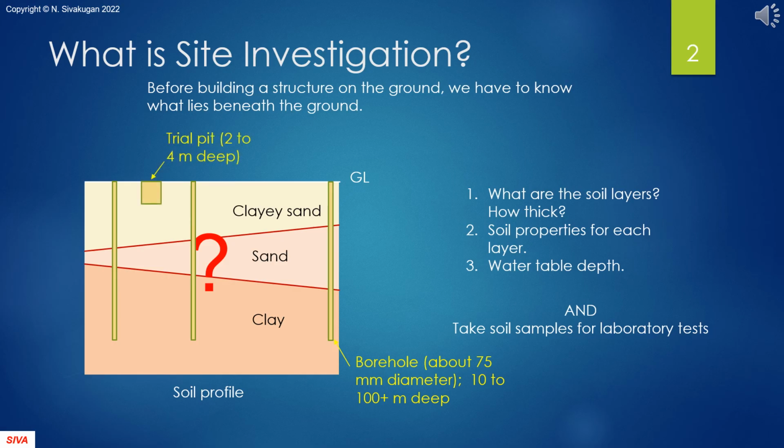There are a few things we have to know. What is the soil profile? What are the soil properties? How deep is the water table? Are there any surprises? We drill boreholes for carrying out in situ tests and for collecting soil samples. We also dig trial pits up to about 4 meters in depth.